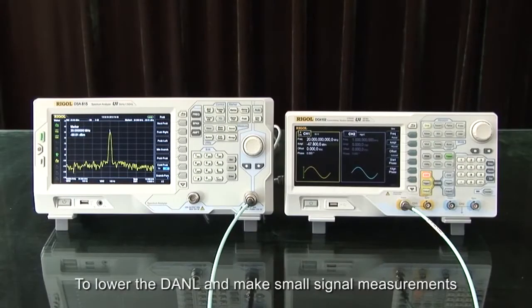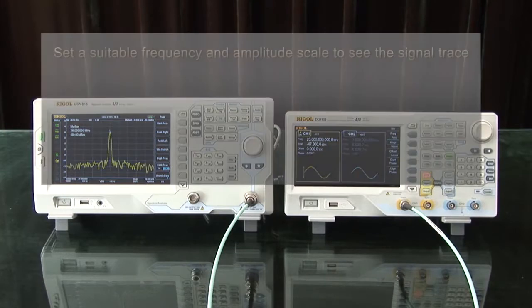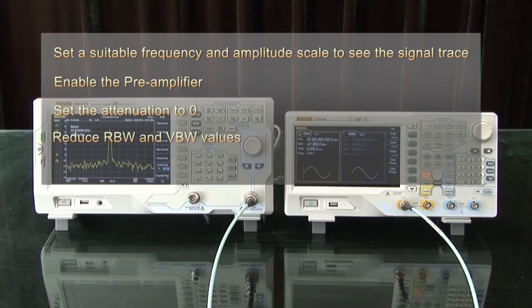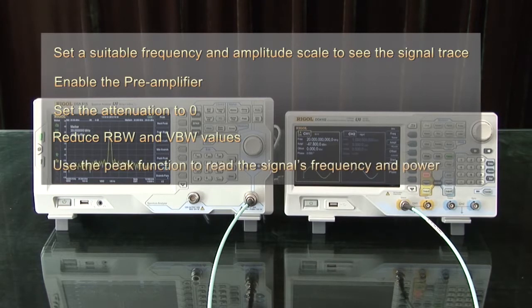To lower the DANL and make small signal measurements, we want to set a suitable frequency and amplitude scale to see the signal trace. We want to enable the preamplifier. We want to set the attenuation to 0 dB, reduce the resolution bandwidth and video bandwidth values, and use the peak function to read the signal frequency input.